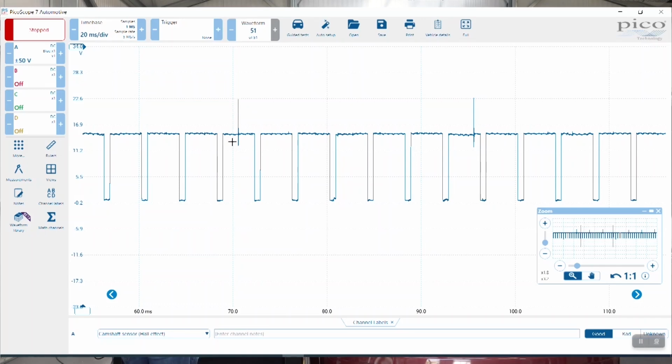We'll talk about interference a bit later, but effectively we're looking at this Hall effect opening and closing, opening and closing. And as John has said, if we bring down our ruler onto here, you will see that we've got 14.98 volts, and our voltmeter was giving us a reading that was different. So, very important to see what there is.